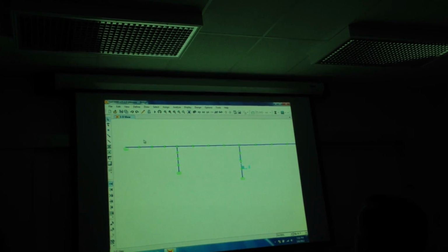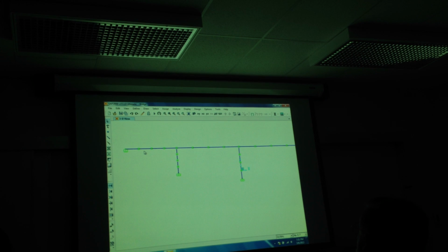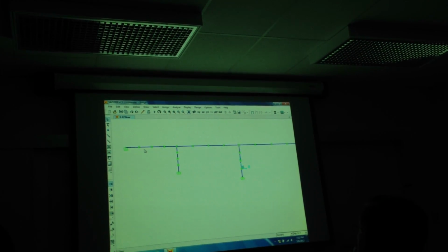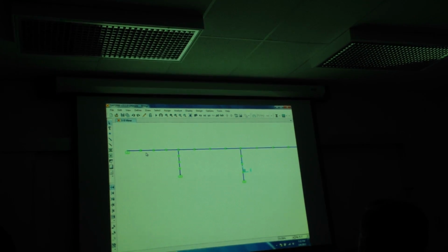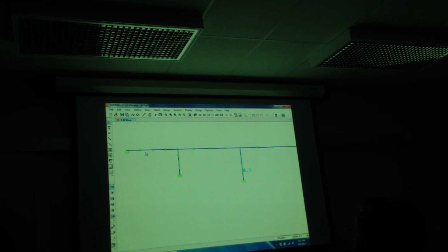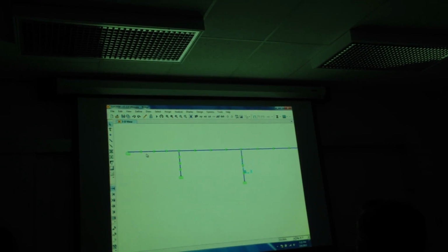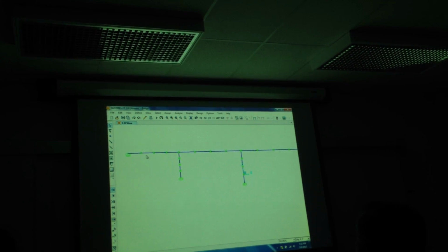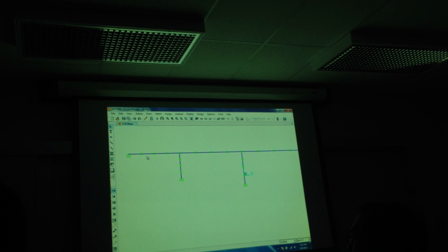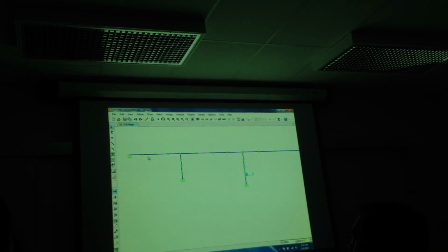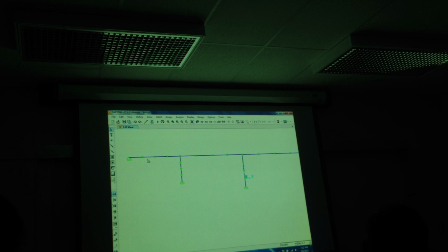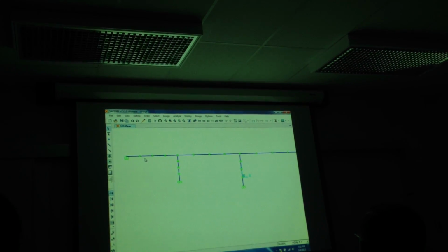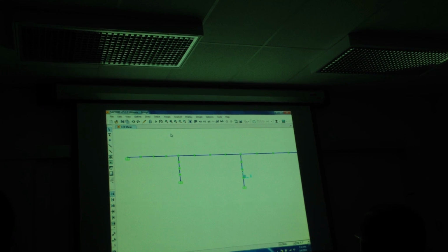The reason I gave it less damping is that we gave it 5% when we do a linear elastic analysis, because there's no hysteretic damping. When we do nonlinear analysis, there's hysteretic damping that occurs in the plastic hinges as it cycles around, and that energy is removed from the system. So more realistic damping for the remaining linear elastic parts of the structure is 2%, not 5%. If you do a linear elastic analysis, people use 5% because they're trying to capture the amount of energy that's taken out through the nonlinear behavior. But if you're actually modeling the nonlinear behavior, you'll see as it cycles around, when it's going nonlinear, it's no longer a straight line, it's looping. Each loop is energy being removed from the system. It's like equivalent viscous damping.